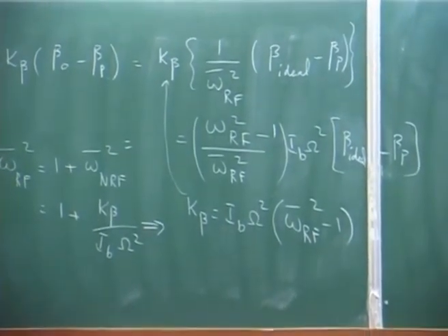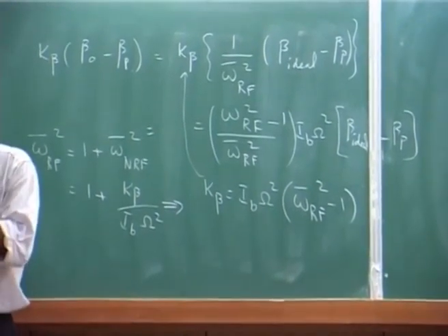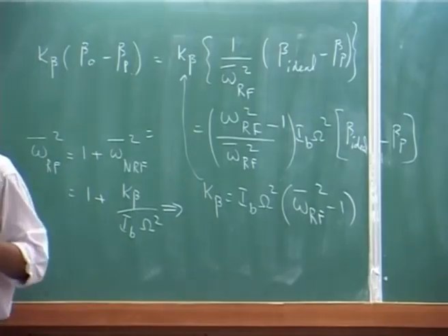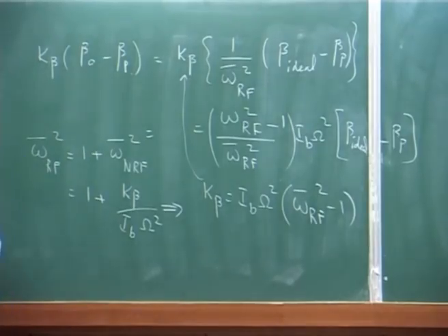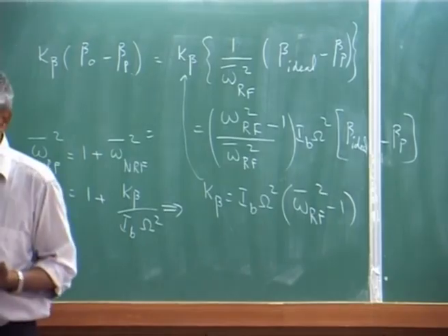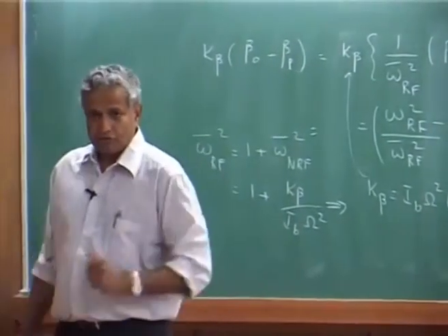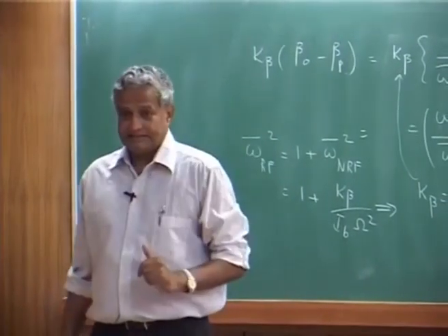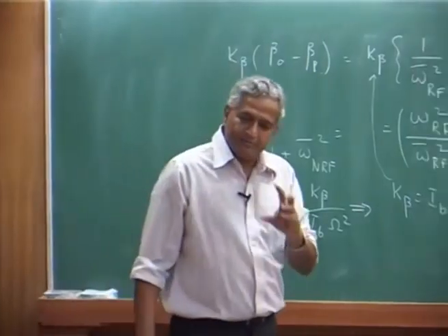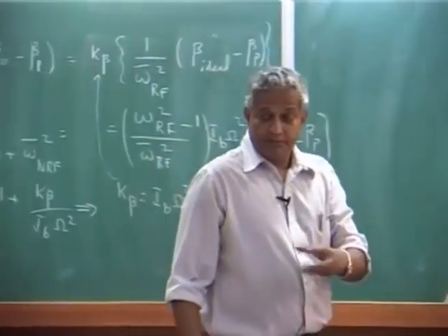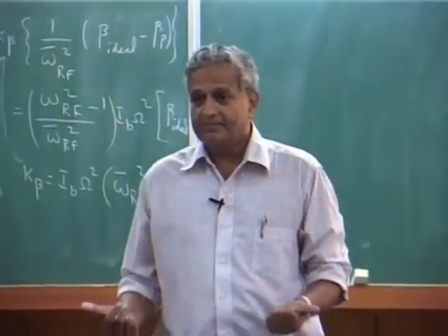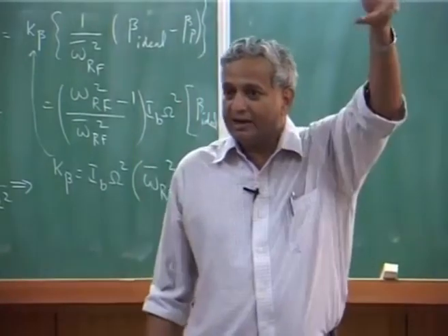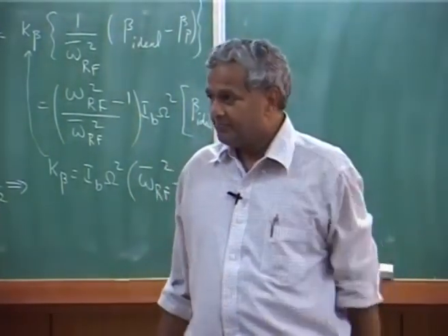See, it is a very conflicting requirement. If you want to maneuver, you need to have root moment, because you want to generate moments. Otherwise, later we will show, you will generate only the moment on the vehicle only by thrust vector. That will have some value, but if you want to have highly agile, you need to generate more moment, then you need to have hub moments from the rotor blades.